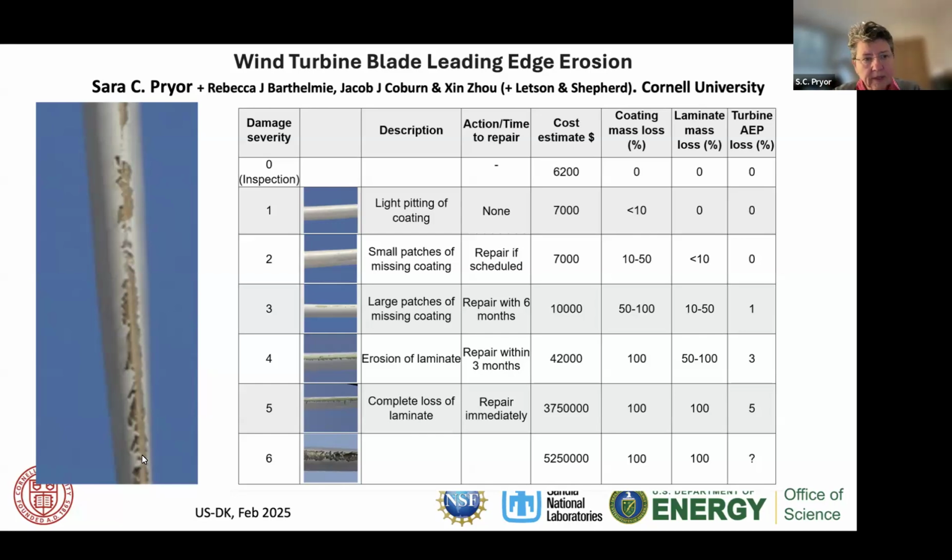so we start to see the underlying structure. As a very crude intellectual framework here, we can think that a wind turbine blade typically has some kind of wooden structure on which is laid glass fiber or carbon fibers with resins that form the real structure of the blade. Then there's a layer of putty, and then there's a coating.